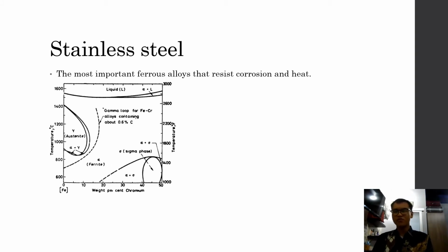One type of stainless steel is austenitic stainless steel, which essentially is a chromium, nickel, iron alloy. The addition of nickel improves certain aspects of corrosion resistance of chromium alloys. The corrosion resistance of this type of stainless steel is usually higher than the other two types, the martensitic and ferritic ones. This type of steel is also highly shock resistant and difficult to machine.